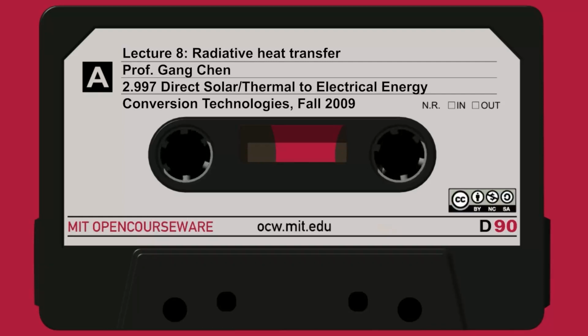So the outside atmosphere is AM0, and then AM1, air mass 1, occurs when the sun is directly overhead. Okay? And AM1.5 occurs when the sun's rays travel through roughly 50% more of the atmosphere than when the sun is directly overhead.